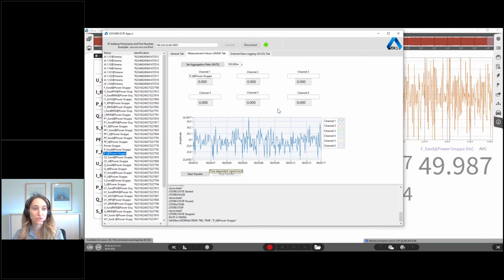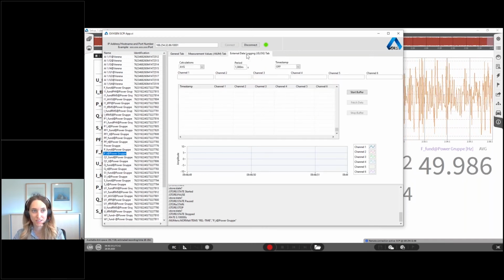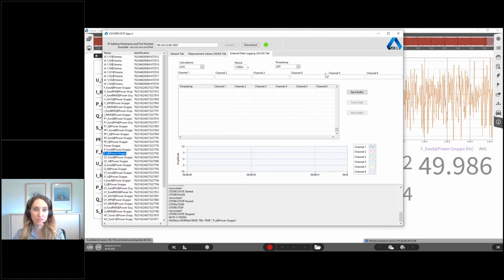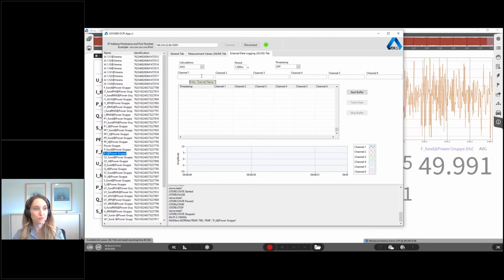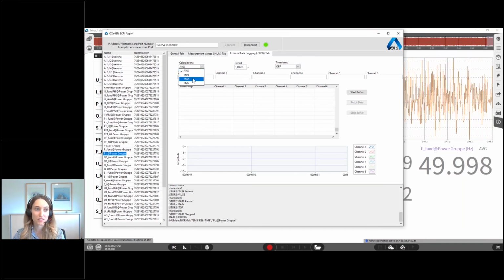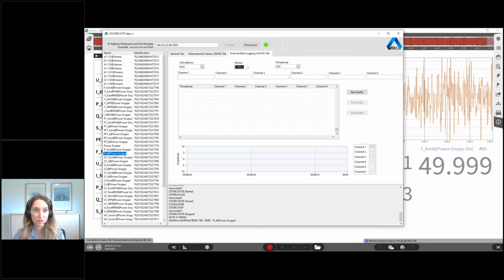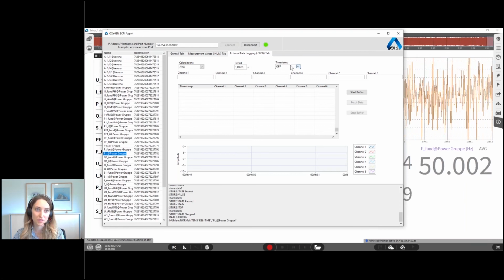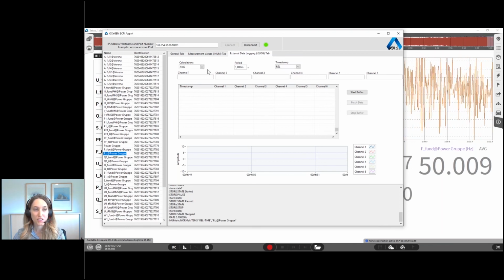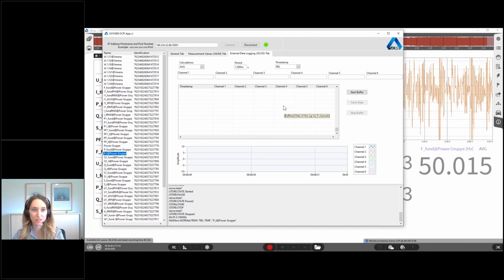Okay, in order to be able to see buffer data, we go to the external data logging or the eLog tab. And we can again see 6 channels can be displayed here. We can choose between calculations, so we can see the average, minimum, maximum, or the RMS value with this period of time. We can set here, and we can choose a timestamp. Here we can see buffered data, or we can access buffered data up to 20 seconds into the past.